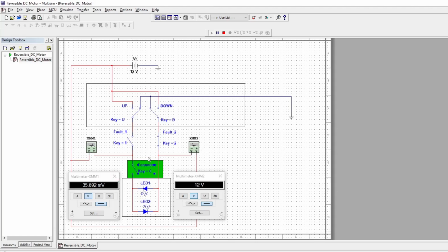All right, so let's just put this back. And it doesn't matter. I'll prove it to you. So now we're going to have a fault over here. On this side, it's still 12 volts. We disconnect the load. This voltmeter does exactly what you think. It doesn't have that path to ground. So now, once you've disconnected it, you know which line has lost its path to ground. So you've literally carved this problem in half.